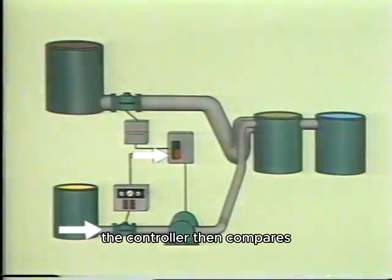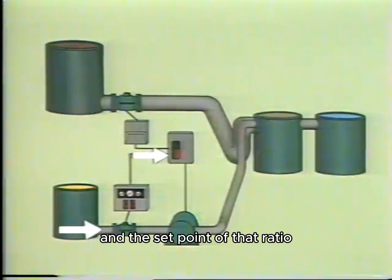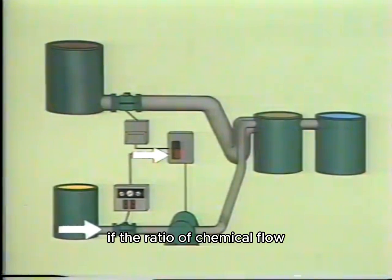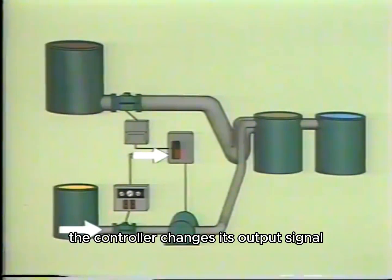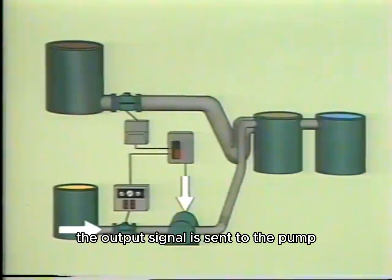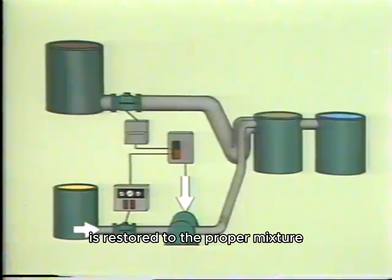The controller then compares the input signal from the chemical flow transmitter to the predetermined ratio and the set point of that ratio. If the ratio of chemical flow input to the new set point doesn't match the predetermined ratio, the controller changes its output signal. The output signal is sent to the pump, adjusting the speed of the pump and reducing the flow of chemical solution so that the ratio of chemical to water is restored to the proper mixture.